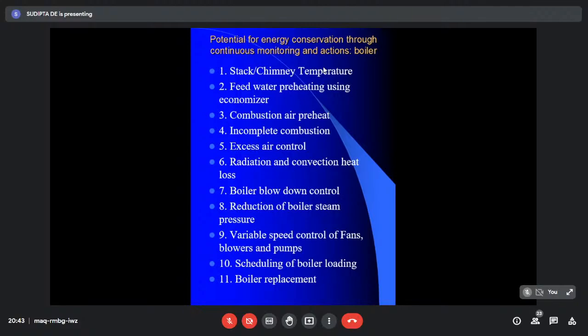So I'm sure chemical engineers know what is stoichiometric, but all of you might have heard this particular term during your chemistry in higher secondary. That means combustion is nothing other than a chemical reaction with oxidant and a fuel. If you write the reaction equation balanced, then you can find out for 1 kg of fuel how much is the oxidant or the air requirement.